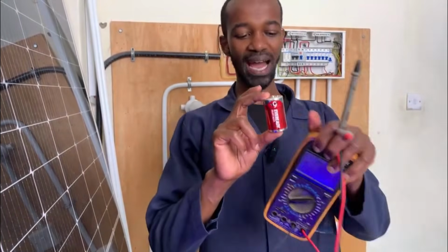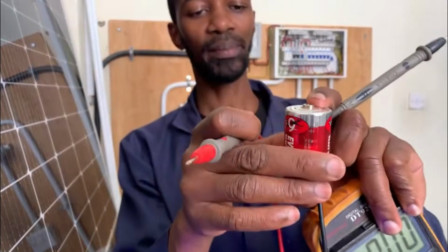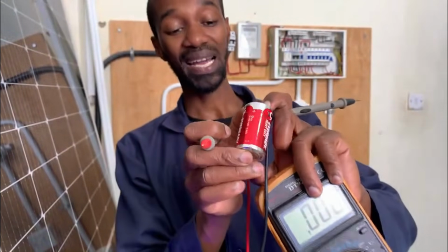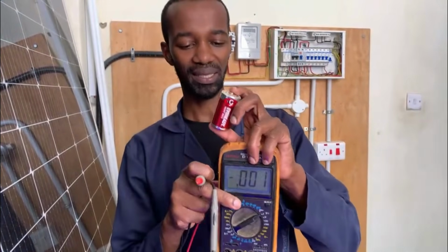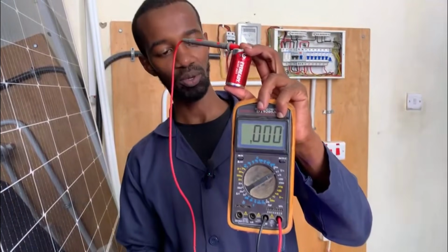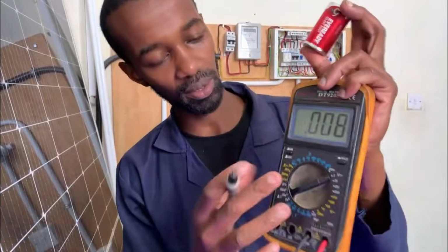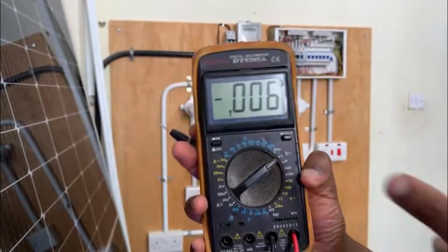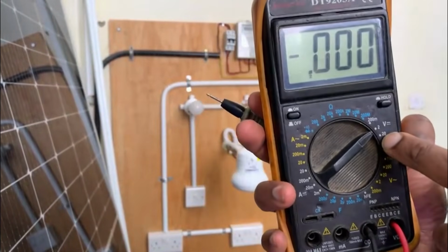Incredible. Now, we will place our probe at this point. We have the positive terminal here and the negative on this other side. This is where I started as a kid. I really understood these batteries, I mean the cells, a lot, because whenever I interchanged the terminals I would be faced with a lot of issues. Now, you see where you place your volt setting before you record the readings. You see where I've placed it, at 2, because I expect 1.5.